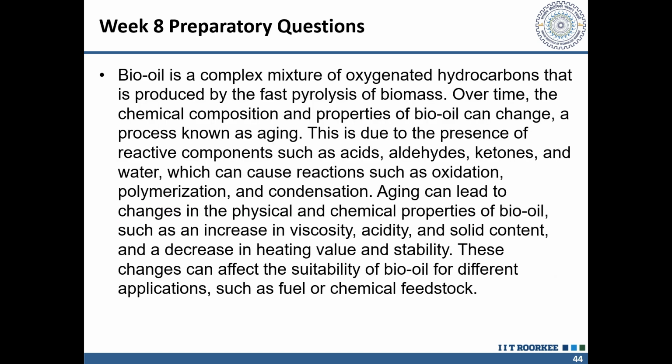So, bio-oil is a complex mixture of oxygenated hydrocarbons produced during fast pyrolysis, and it has very highly reactive components such as acids, aldehydes, ketones, and water, which can cause reactions such as oxidation, polymerization, and condensation. Therefore, aging will lead to an increase in viscosity, acidity, and solid content.